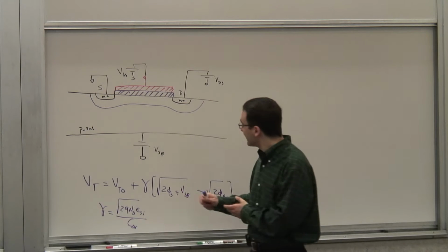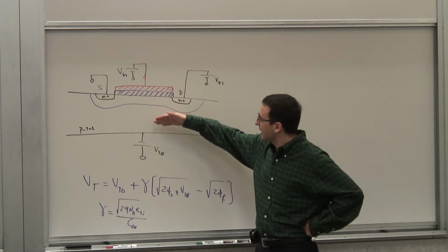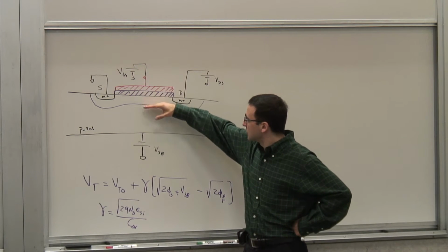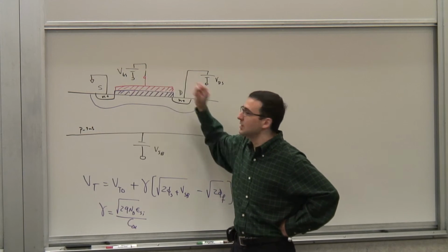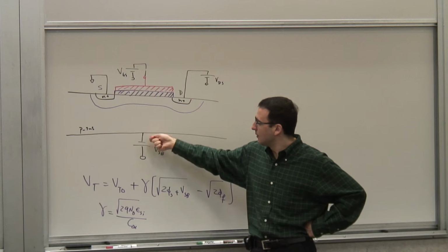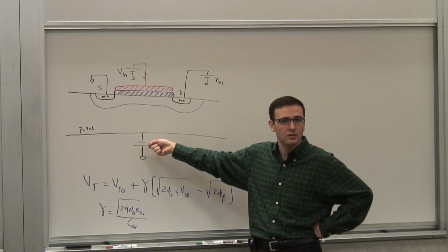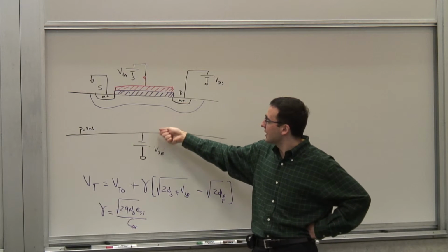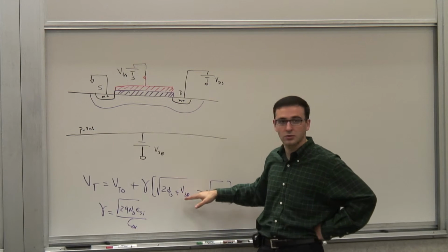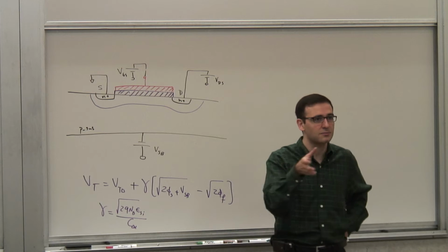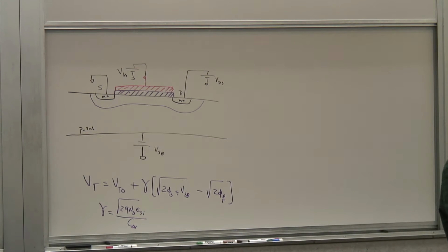But we saw that there is a secondary effect, this body effect, that can control the current, because if you keep these other voltages constant, let's say your VGS and VDS are constant, right? And I apply voltage here, the substrate, the bulk. What happens is that I can actually control the drain current. Why? Because I'm changing my threshold voltage, and the threshold voltage appears in the expression for the current, which is as if I'm changing my VGS.